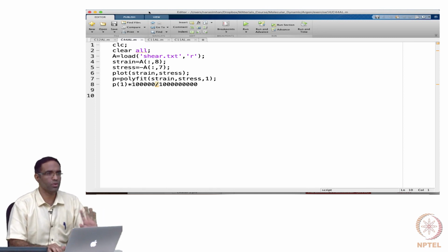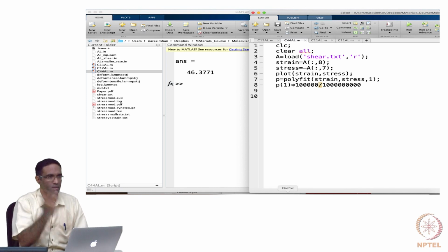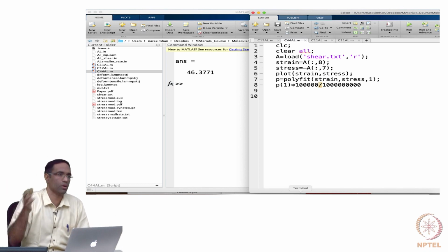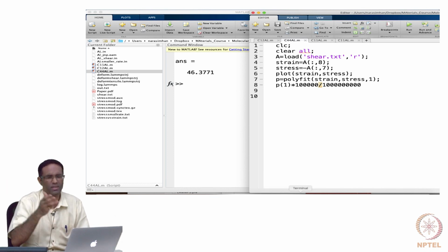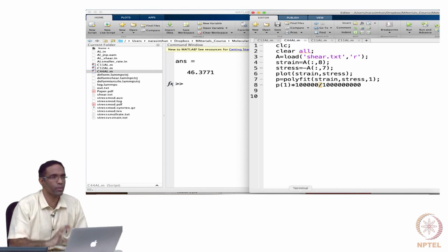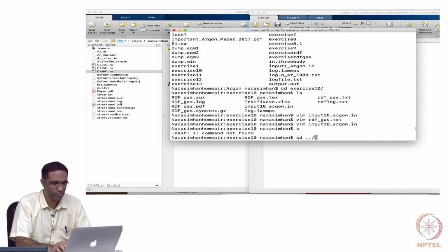That's fine. So, basically it helps you to represent a second order tensor as a vector, right? The stress and the strain, and then you are able to represent the fourth order tensor as a second order, as a 6 by 6 matrix. Okay. You can refer to any standard books on elasticity, you will find what exactly that means. Okay, it's very simple. Now, I want to focus on writing these input scripts.